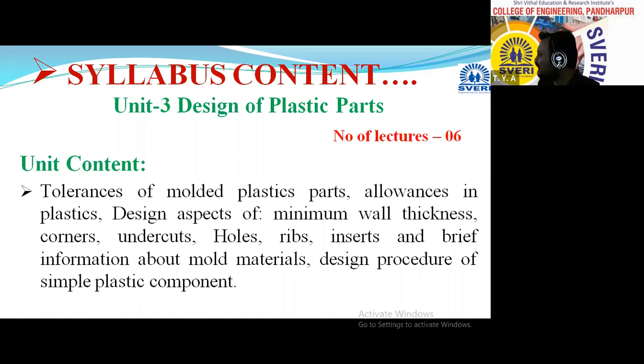First, we will check the factor of safety, related to how much strength is required and how much load will be there. As 4 legs are there, that load will get distributed on 4 legs equally. Then how much weight will be there on one leg? Because on each leg there will be a separate bush. This chair is also having 4 legs. 4 bushes I am going to add, but the designing will be the same. How much load will be there?